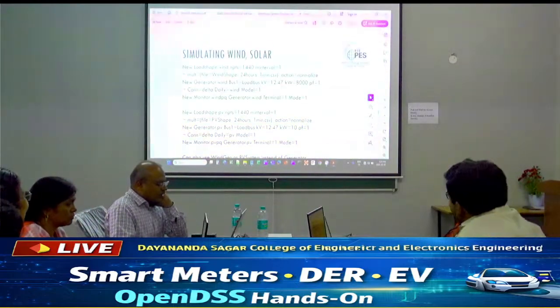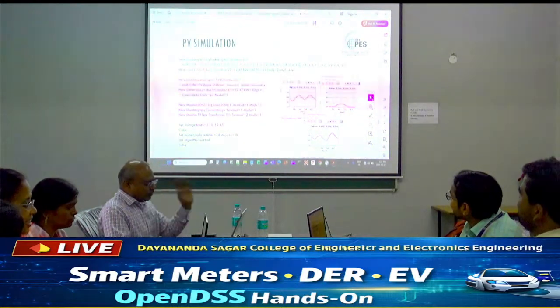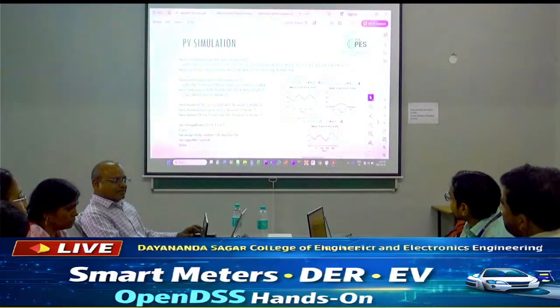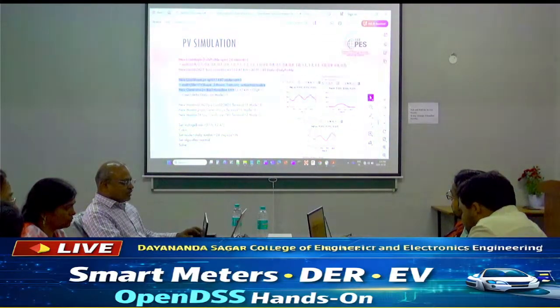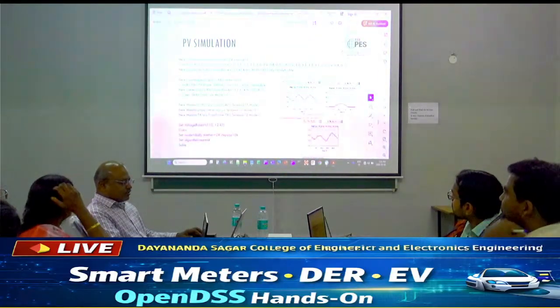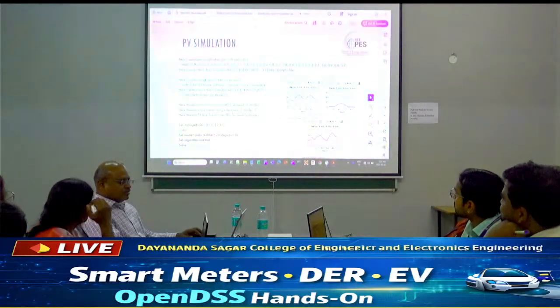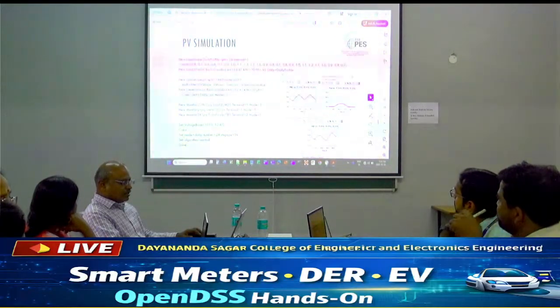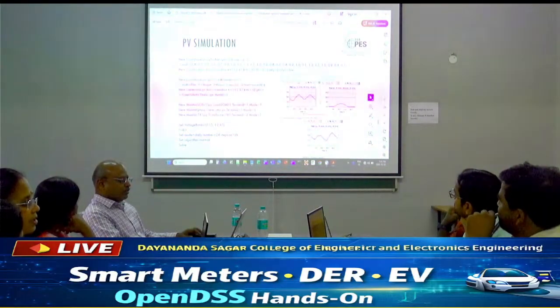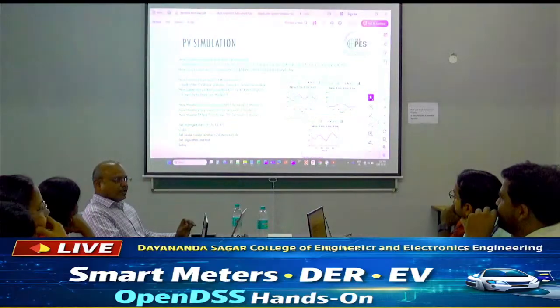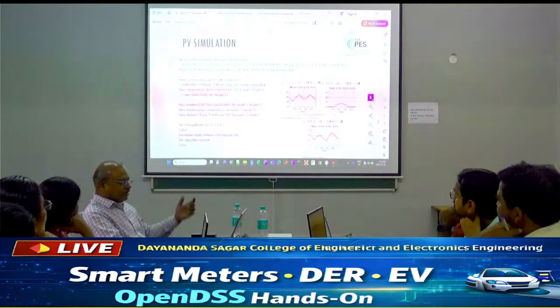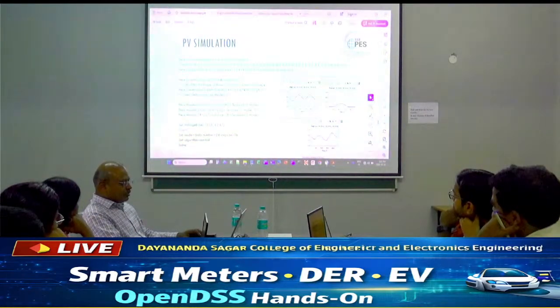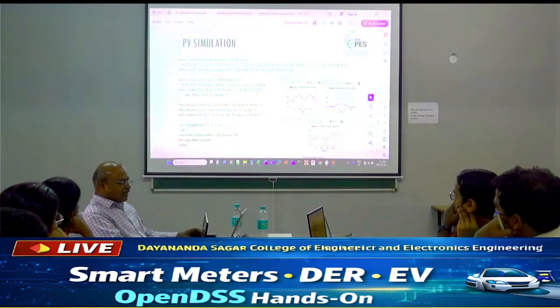So basically you define the circuit, right? And this is how you define the solar, right? So you define a load shape, right? So we are saying here number of points is 1440. Why is 1440? Because we are giving it every minute. So 24 hours, every minute, so 60 into 24, right? So that many points we give, and we mention it in a CSV file.